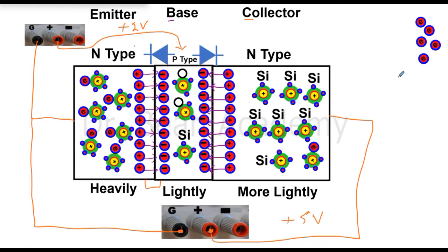So, the base is at plus 2 volts. Then we have ground, which is in the middle, lower than plus 2. Current will always flow from ground to the plus 2 terminal. Plus 2V is more positive than ground, so ground will work like a negative terminal. The N-type side of this PN junction is connected with the negative terminal, and the P-type side of this junction is connected with the positive, and this is in forward bias mode according to the definition we know of the PN junction, which is now part of a transistor. So this junction is in forward bias mode.